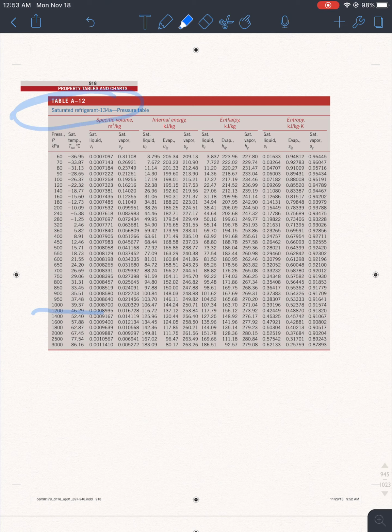So in this case, it's somewhere around 5 versus 1. And 5 is greater than 1, so it's a real system. It doesn't break the rules of thermodynamics, because the coefficient of performance over here is not greater than the maximum. So, okay, that explains these two.